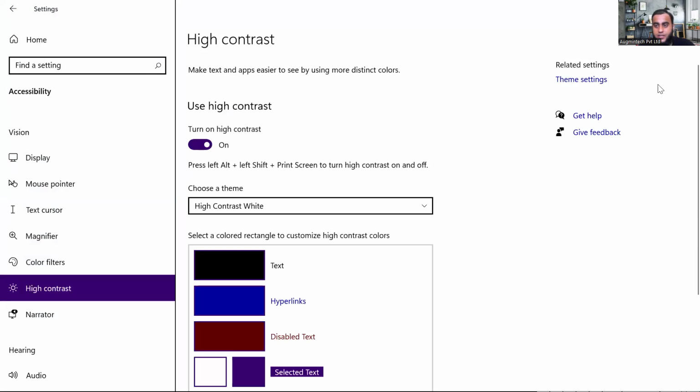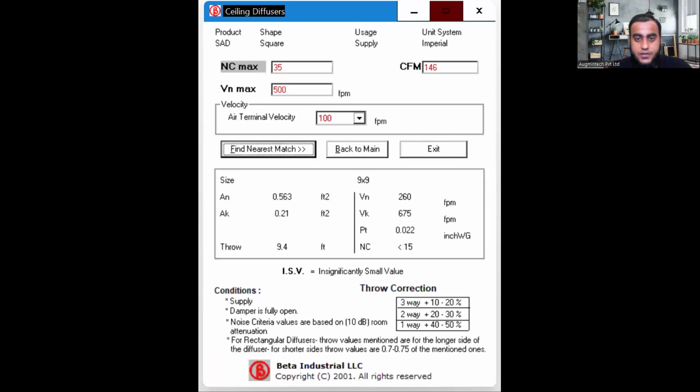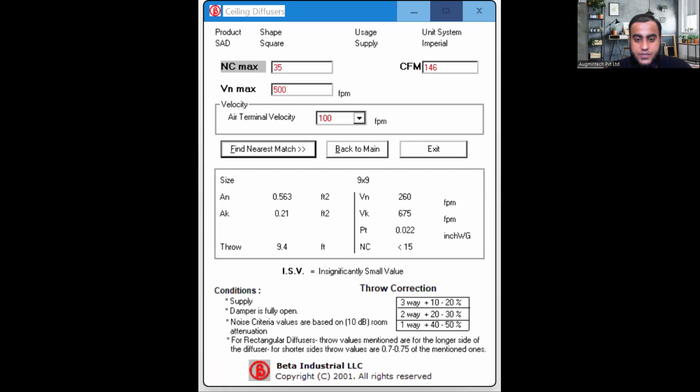Now, can you see? Here we have done the changes. Now, finally, when I'm opening that software, now you can easily view that. Tell me, please. Now it is visible, the duct size and everything. How much size of duct is showing here? See, 9 inch by 9 inch. 9 inch means how much? 9 into 25.4. It's near about 250, no? 228 point something means 250 by 250.